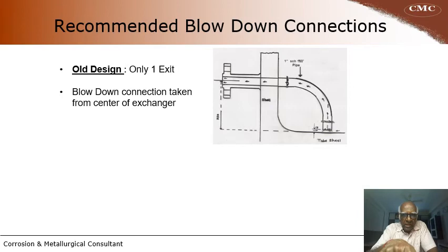The blowdown connections are given in detail in this slide. You can see in the old design, there is only one blowdown exit coming from the center, a blowdown connection taken from the center of the exchanger, and this is not sufficient to take all the stagnant water.